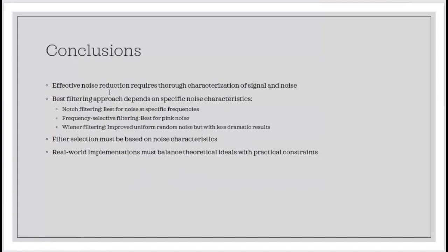In this project, I used techniques like zero-phase filtering with filtfilt to mitigate phase distortion, an approach possible for offline processing but not in real-time applications. These practical constraints highlight why filter design must balance theoretical ideals with implementation realities.